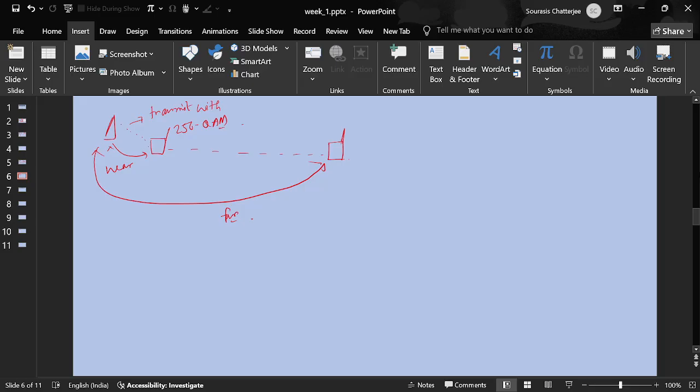Okay, true. So let's say the base station is still transmitting with 256 QAM to that user. Now of course the user would not be able to receive the message properly. So this is where your ARQ comes into the picture. The user is supposed to send the acknowledgement back, as you correctly pointed out, saying whether the earlier transmission was successful or not, and only then the base station usually proceeds with the next transmission. As of now, we are assuming that the transmission is being acknowledged even if we don't mention it.